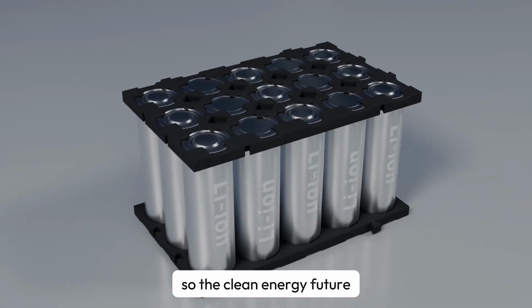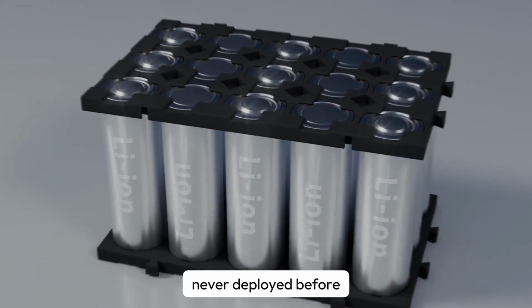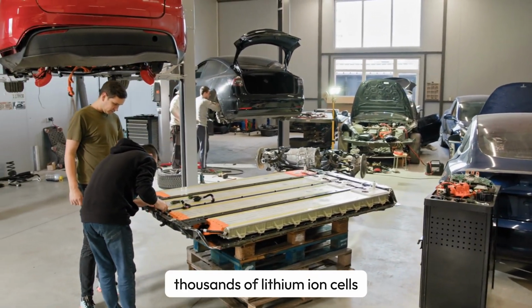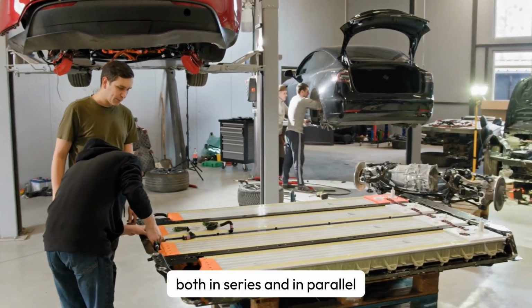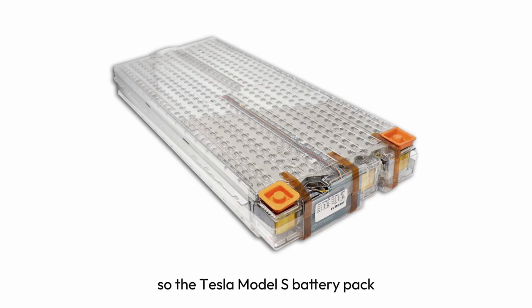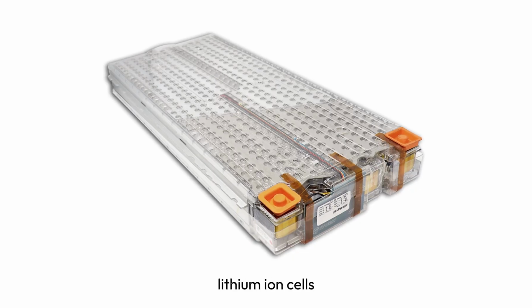So the clean energy future depends on batteries at a scale that we've never deployed before. So electric vehicles have a single EV battery pack that contains thousands of lithium-ion cells that are connected both in series and in parallel. So they deliver hundreds of volts at hundreds of kilowatt hours of energy. So the Tesla Model S battery pack, to name one example, contains about 7,000 to 8,000 individual lithium-ion cells.